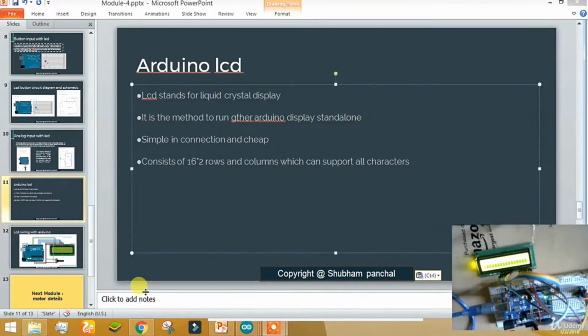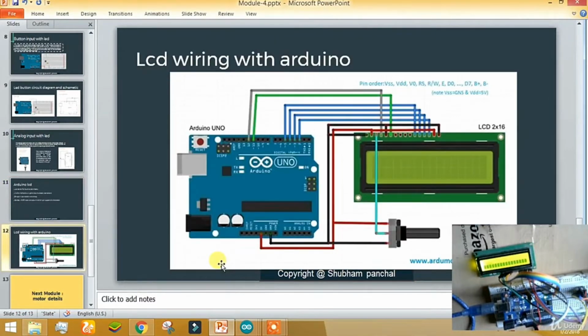Okay, now let's see the block diagram of the LCD. Here is the schematic of the LCD. Remember these important things: these pins are for the light, these pins are for the power, and this important pin is for analog display. If you rotate the dial, it will give a value that will make the LCD go dark or dim. I will show you. You can see that by rotating the dial, the potentiometer, the display of the LCD changes and gives us a dark or a light view.